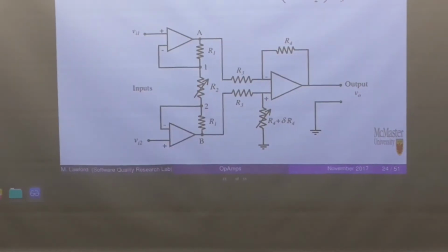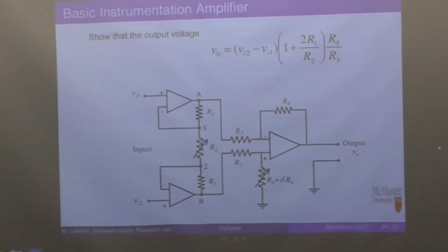I know that it violates our ideal op-amp laws, but our ideal op-amp laws are also ideal laws, so it's possible that one of the factors that we're ignoring might come in to save the day, but I wouldn't bet on it, basically. So don't make that resistor 0. That's the long and the short of it.